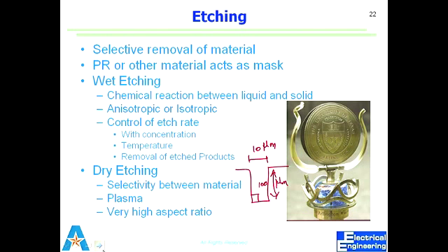Essentially, the idea is that, in this example, we used a dry etch process, and at the end of the etch, we got 100 micron depth, but the etch did go on the sides. If it had gone like this, we would have called it isotropic etch. It should have affected all directions in the same way. Hang on with me, we'll see what isotropy and anisotropy are.